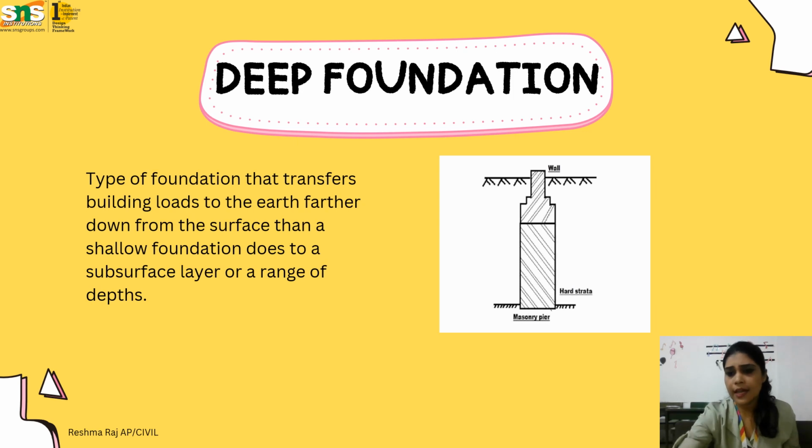As for the load capacity, deep foundations are designed to support heavy loads and distribute them to deeper or more competent soil, or rock layers beneath the soil, the real rock layers. This enables them to bear the weight of tall buildings, bridges and any other large massive structure without excessive settlement or instability. The ultimate problem of a building is the settlement that causes collapse of the building. So to reduce that, we take extra care to prevent the settlement. For preventing settlement, selecting the foundation plays a very important role.